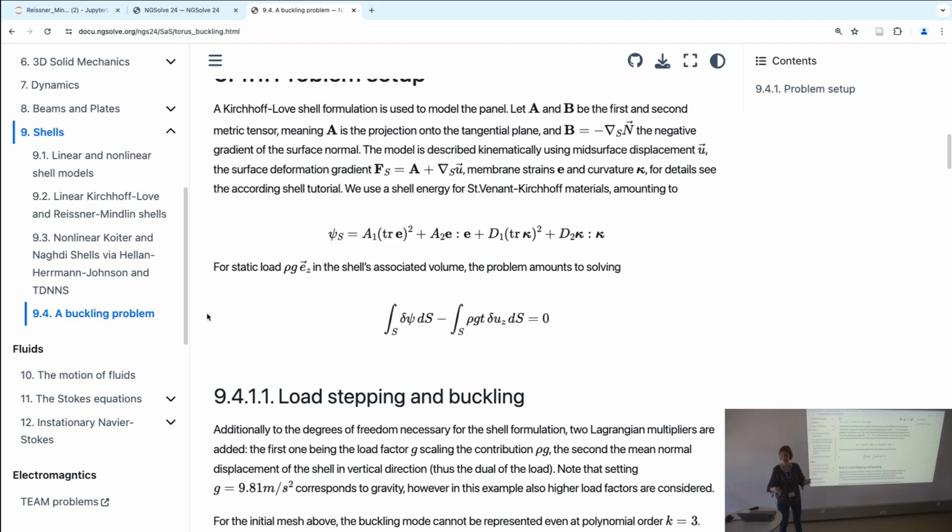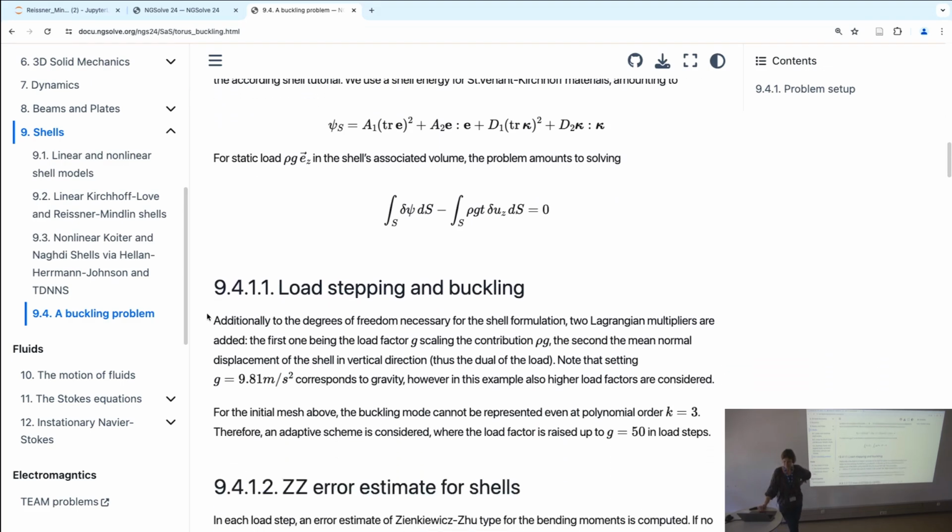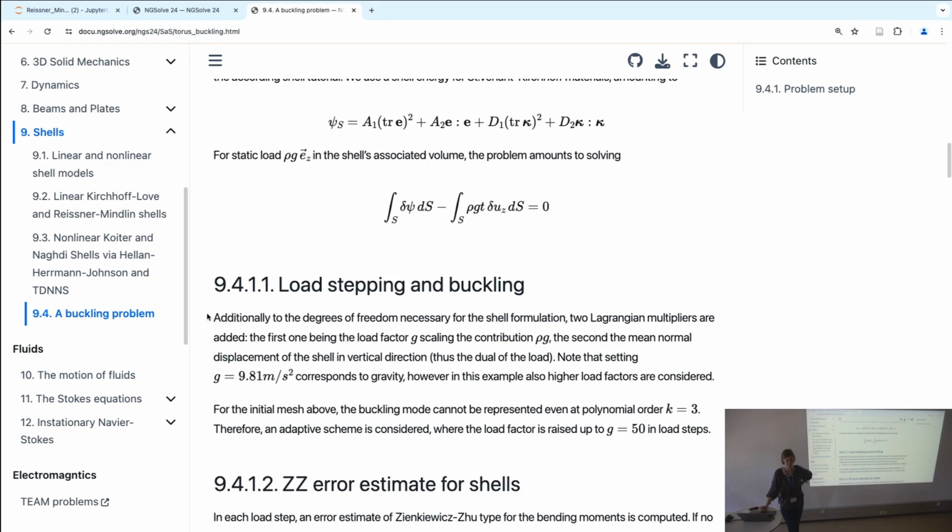All we need to do is add the additional overhead, let's say, to make things compatible. We add bending moments to have the kinks in the surface due to the nodal H1 elements. We add bending moments which make the kink a continuous transit from element to element, like you would if you had a hinge.